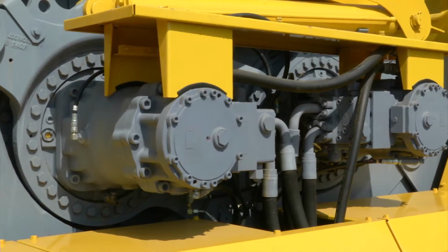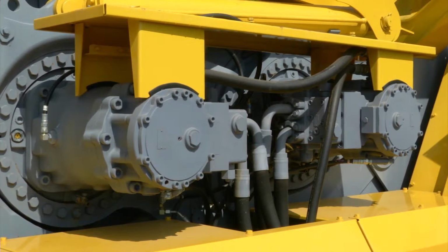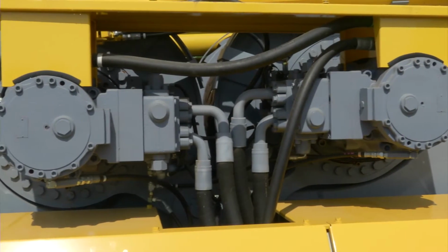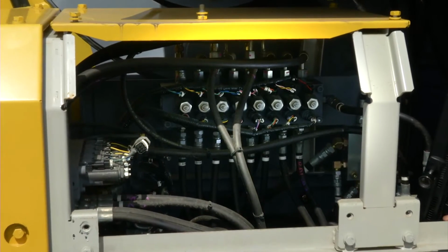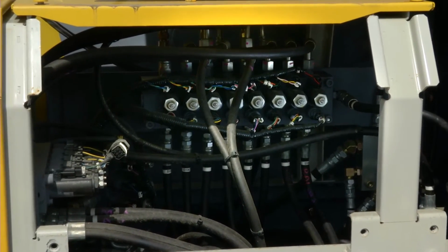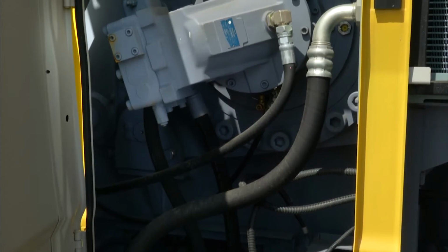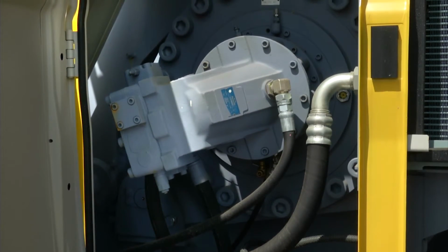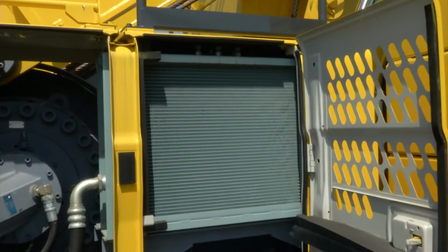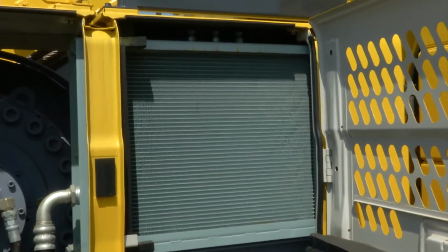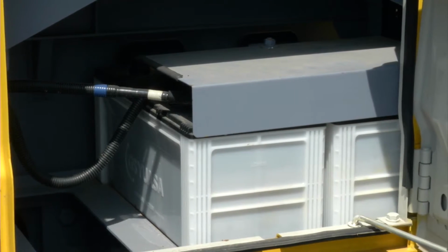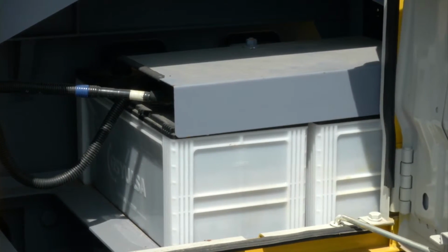On the left side of the machine behind the top cover, we have the front and rear winch motors and gear reduction units with oil level sight glasses. These are situated for easy access. Below the winch motors behind the bottom cover are the pilot control valves. Behind the first door are some of the main control valves and the boom hoist motor. The next area contains the auxiliary hydraulic oil cooler and two 12-volt batteries hooked in series to supply 24 volts of power to the machine.